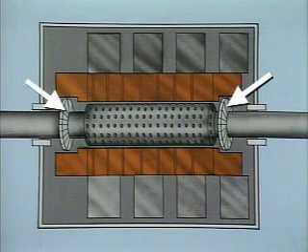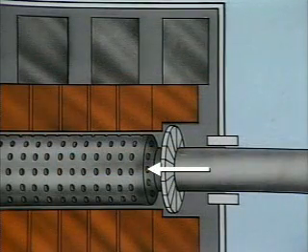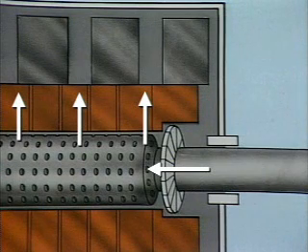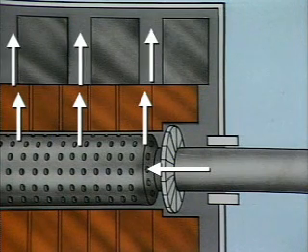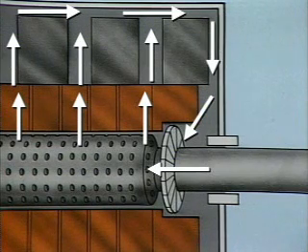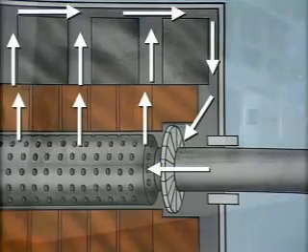Two circulating fans are mounted on the rotor shaft. The circulating fans push hydrogen through holes in the rotor and past the stator. After it passes through the coolers, the hydrogen returns to the circulating fans to go through the cycle again.